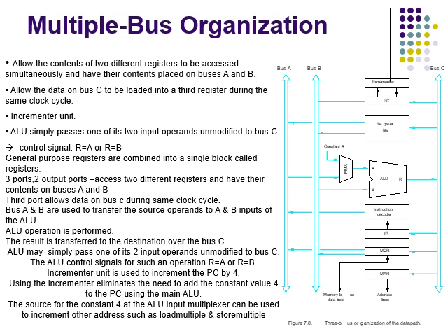We used the single bus structure to illustrate the basic idea so far. So the resulting control sequences which we have discussed are quite long, because only one data item can be transferred over the bus in a clock cycle. To reduce the number of steps, most commercial processors are provided with multiple internal paths that enable several transfers to take place in parallel.